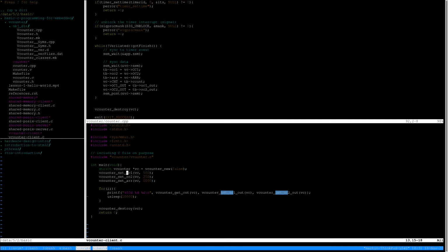That's kind of the whole point. You can take a Verilog file and compile it into C code. Verilator is a compiler that generates C++ code from Verilog, and it's used for simulation purposes. But you can also take that generated device and instantiate it inside a process and share the state of that device with other applications on the system, so you can run simulations against that device from other applications on the system.